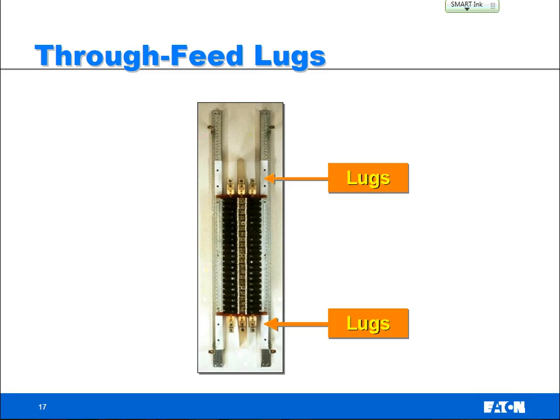Think about life safety. You've got to have a separate feed. You don't have a whole lot of load, and you'll have 4 floors of panel boards. They'll run power from floor 1 on the lugs out the other side, and this goes up to floor 2, and the bottom out the top up to floor 3, and it saves you some cable, and it saves you a lot of extra feeds up to those different panel boards.